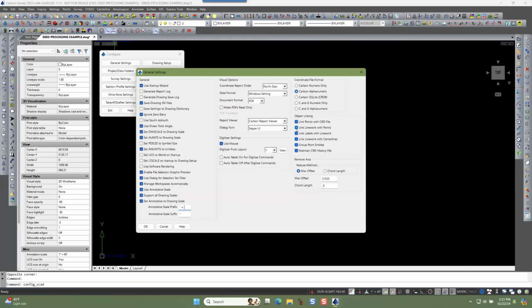Then if that linking is on when you create the labeling, it will update when the geometry of the drawing changes, the labeling will recompute and go along for the ride. Same thing, linking line work with center lines. So if you have created a center line file out of some drawn line work, then this is a two-way link so that if you edit the centerline file by typing in some different numbers in the file, once you save and exit the editor, it will redraw the line work. Or if you just grip edit the line work inside the CAD system, just using a CAD command, then it will automatically update the centerline file.